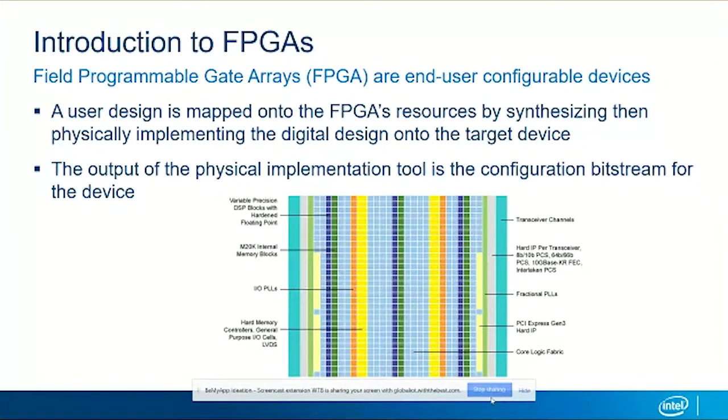So when you implement your design using partial reconfiguration, the design is going to be implemented into a mix of these resources. And how you select the area of the floor plan will determine how many resources are available and how the design needs to be implemented, which will impact the performance of the design.